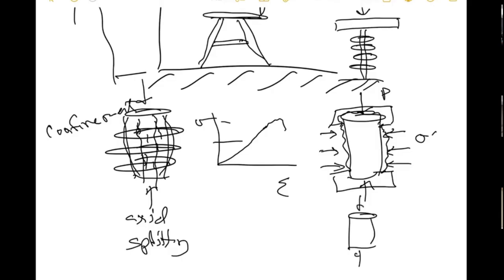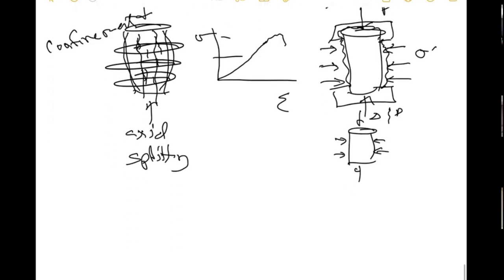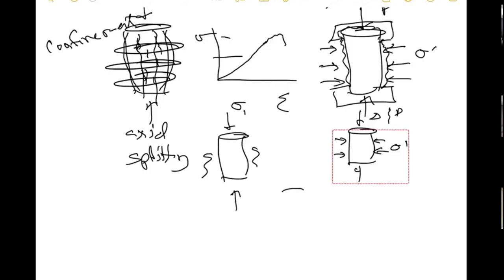Pressure, they actually apply delta, right? And they measure P, so they're applying P, and they maintain this pressure. It's usually a hydraulic system, some kind of hydraulic fluid, and they maintain this constant. And we call this a triaxial test, because now the material is not only being loaded this way. In this system, that's sigma 1, and there's nothing here, it's 0. But now it's loaded like this, sigma 1.